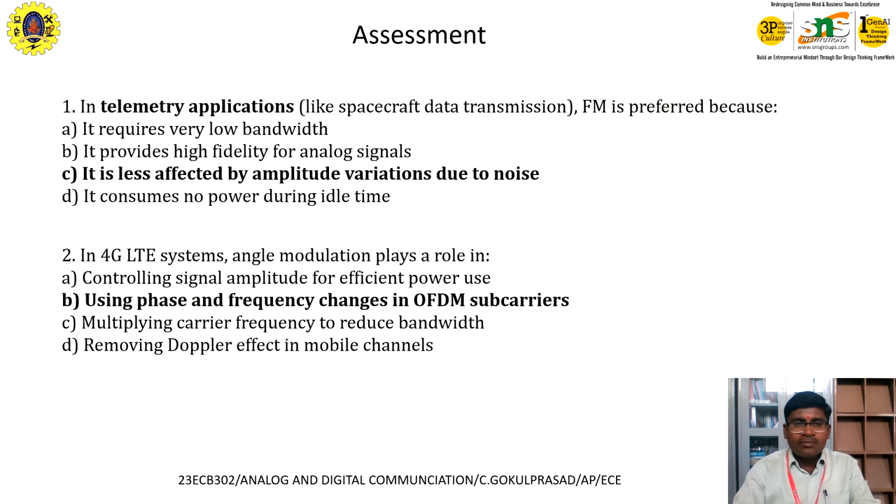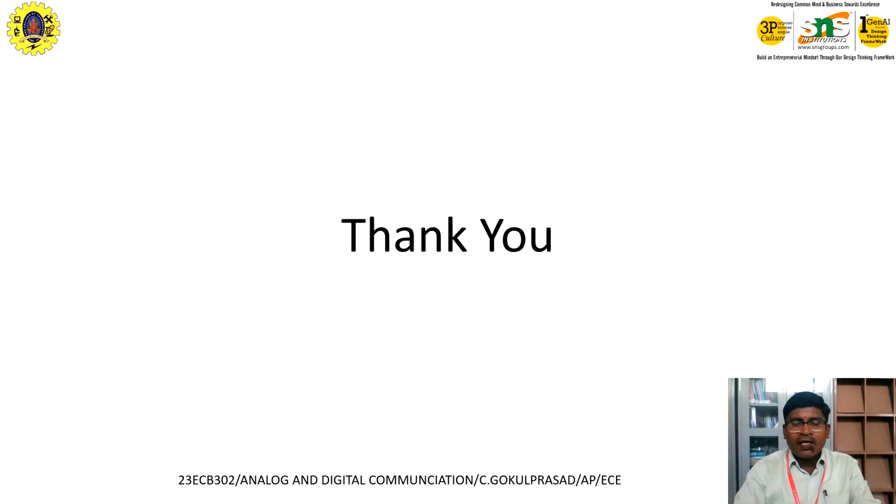Coming to the assessment part, in telemetry applications like spacecraft data transmission, FM is preferred because it is less affected by amplitude variations in noise, right? Coming to the next question, in 4G LTE systems, angle modulation plays a role by using phase and frequency changes in OFDM subcarriers, that is orthogonal frequency division multiplexing subcarriers. So this is about the assessment part.